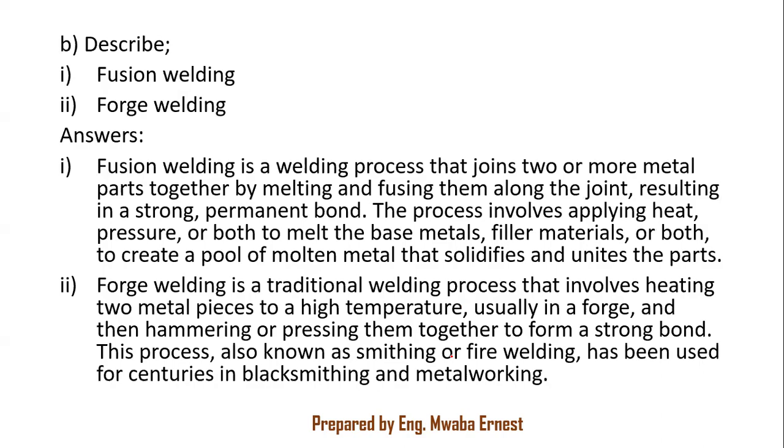It involves heating the two metal pieces at high temperatures, and then you can start the hammering and processing, making sure it retains the shape you're looking for. And should there be any induced, trapped stresses, it's very easy to deal with them at this point. So the forging processes are done after you've heated the material.